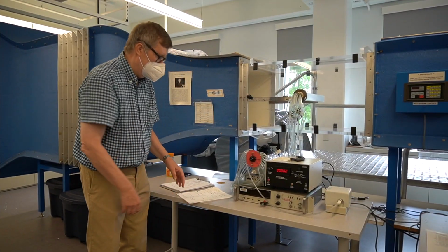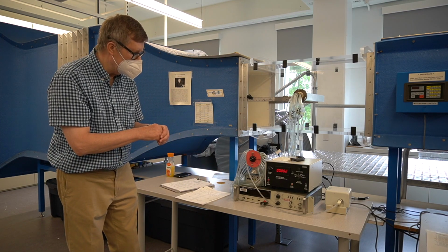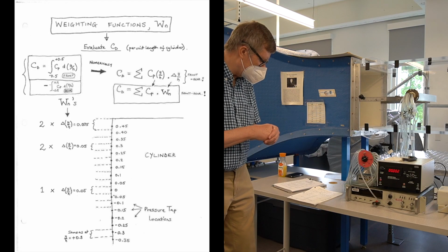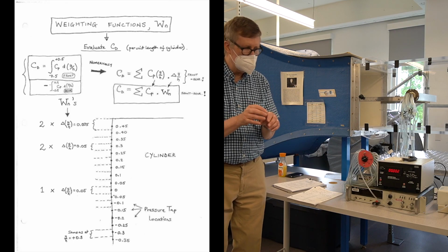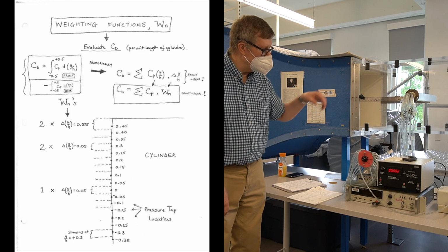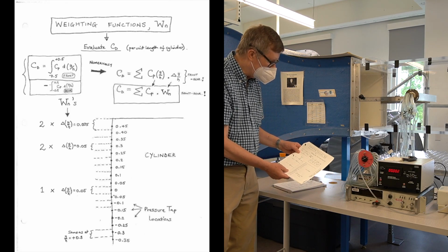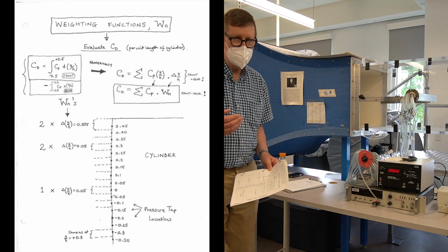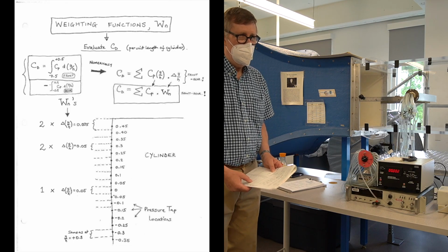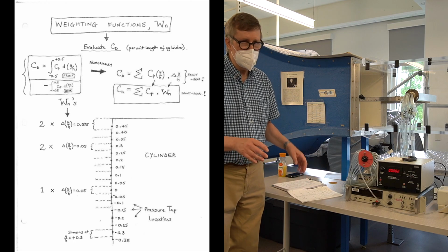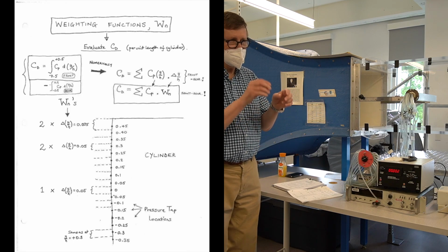There's different ways of getting from that point to an actual pressure as well. So basically, through this table here, I'm not going to go into detail on this. It's not worth it at this point. But basically, when you want to get a drag coefficient, you're measuring coefficient of pressure times little areas each time. And because of the geometry of the setup, you get weighting functions here that are equivalent to little areas. So basically you're measuring pressure coefficient or pressure difference and multiplying it by the area over which that pressure is assumed to occur. And then you get pressure times area, and you get little bits of force.